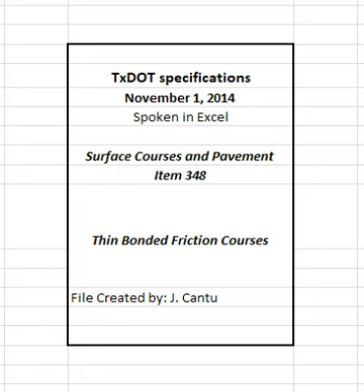3.1.1.2 Membrane storage tank and distribution system. Equip the paver with an insulated storage tank with a minimum capacity of 900 gal. Provide a metered mechanical pressure sprayer on the paver to apply a uniform membrane at the specified rate. Locate the spray bar on the paver so that the membrane is applied immediately in front of the screed unit. Provide a readout device on the paver to monitor the membrane application rate.